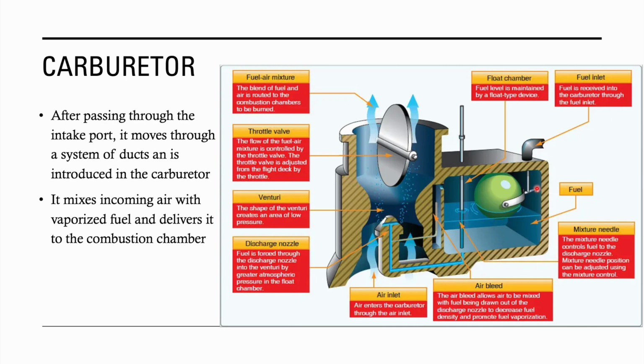You can also think about this like the tank on the back of your toilet. Whenever you flush, water comes from the tank, goes to the toilet, there's a ball inside there that drops, it opens a valve, and lets more water fill up the tank. Same thing is happening inside this carburetor. This float drops, there's a fuel inlet, and it lets more fuel inside this chamber. That pushes the float up, and then that shuts off the fuel inlet. Usually, as you're flying, you're burning up fuel, and so this float will drop a little bit, so you're continuously letting fuel in and burning fuel.